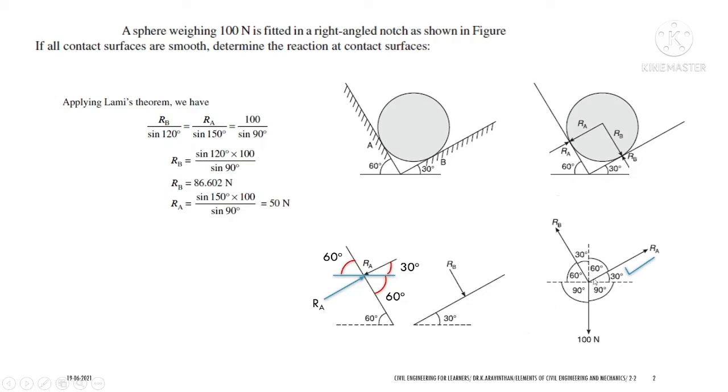So this is what is written here, the same force being transferred to the point. Let us take the next reaction, RB, and draw a straight line here. If you draw a line, there will be a force and a reaction, and let us take this as RB. After drawing this horizontal line, we know that this is the same angle, 30 degree. The opposite angle will also be 30 degree. Since the load is perpendicular to the surface, 90 minus 30 will be a 60 degree angle. So this is what we have written here: RB is 60 degree from the horizontal.